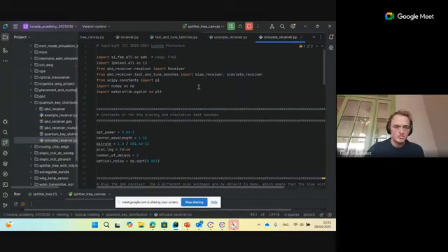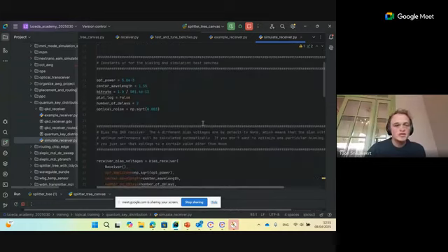So first we have the import statements. Then here you see the information about the inputs, the pulse train: the power, the central wavelength, then the bit rate. We see it's 581 picoseconds is the period between two pulses. And for that we choose two delays, which are two spirals. And then we can also specify the optical noise of the signal.